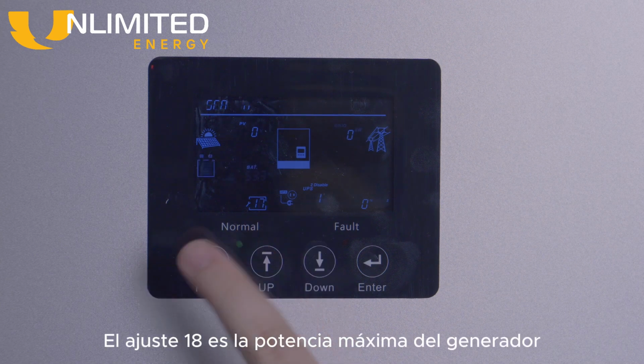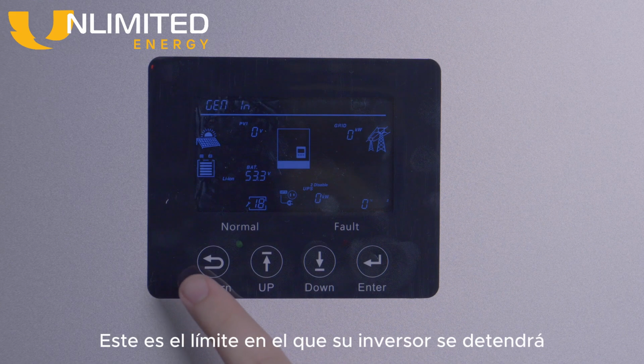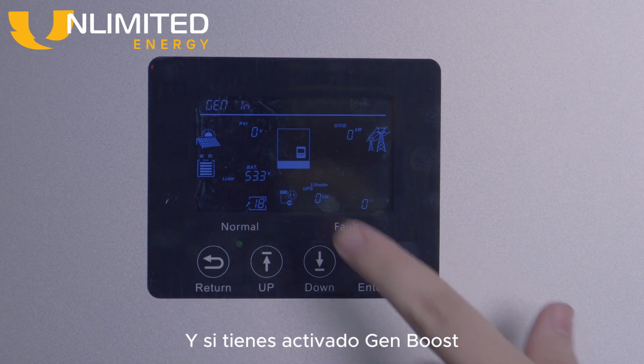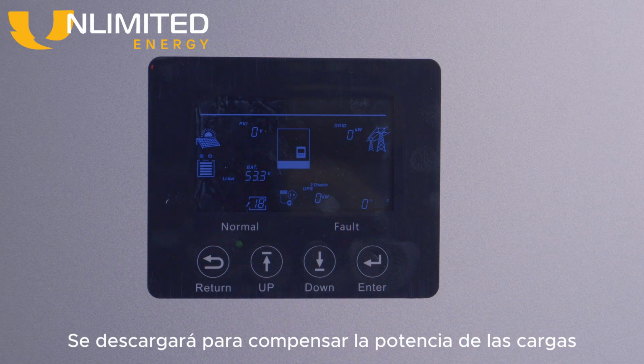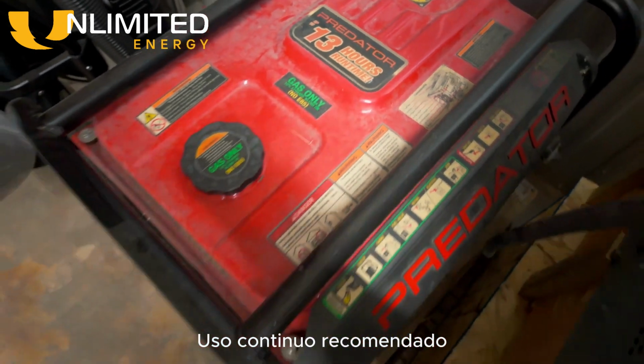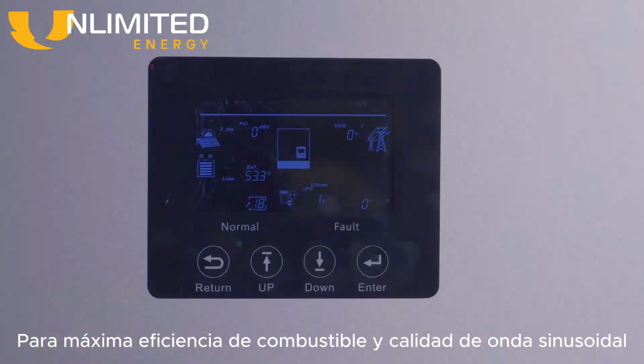Setting 18 is max generator power. This is the limit at which your inverter will stop charging batteries from generator, and if you have Gen Boost enabled, will discharge to compensate power to loads. It's best to set this to your generator's recommended continuous use for maximum fuel efficiency and sine wave quality.